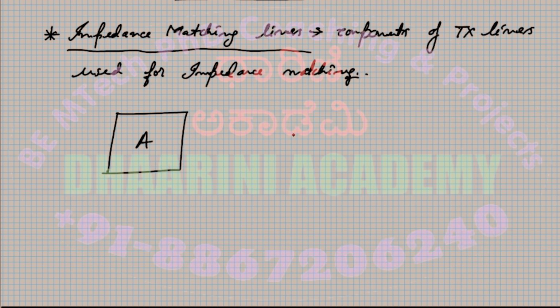When I say I have a fixed source, what is the ideal case? The ideal case is to choose a load whose resistance is equal to the resistance of the source, correct? So the problem looks very simple. I have a source whose output resistance is say 10 ohms. Now you should select a load which also matches 10 ohms. That's my problem. But normally that is not going to happen.